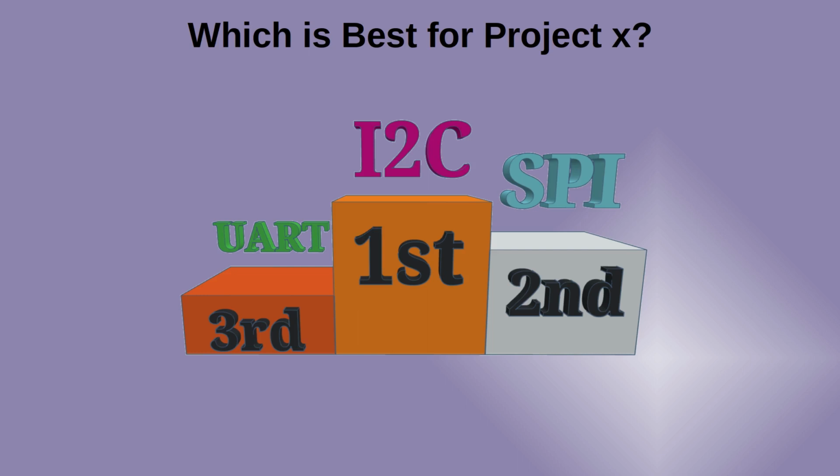The fact is, it's really too close to call. You could just as easily use I2C or SPI, but the crucial thing is that I've already created a video on SPI and not on I2C, so this gives me a reason to use I2C. The project is real though, and I probably will use I2C, just because it uses fewer wires. Even though the result is close, it's worth going through an evaluation exercise for each project rather than just going with what you've used before. Hopefully I'll be creating this project over the next few weeks.